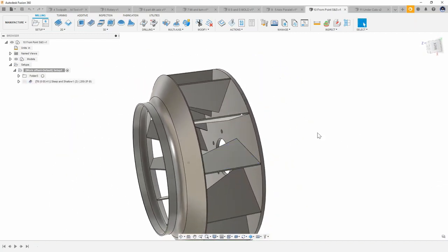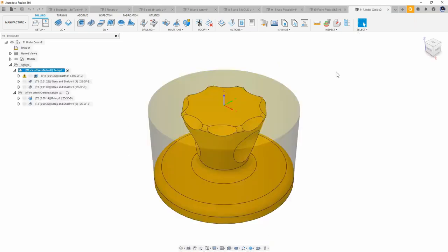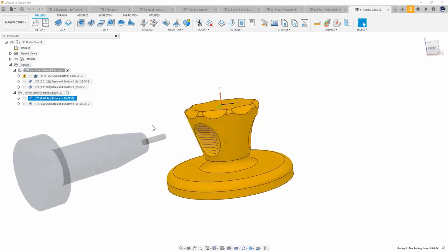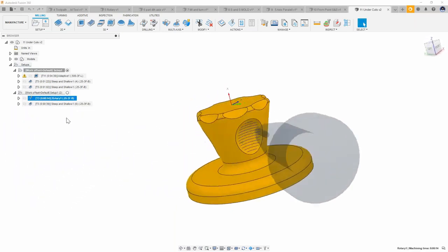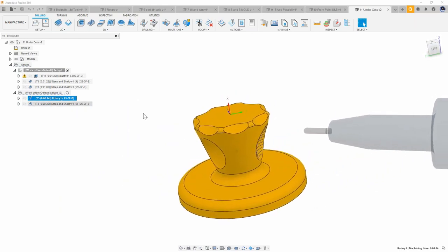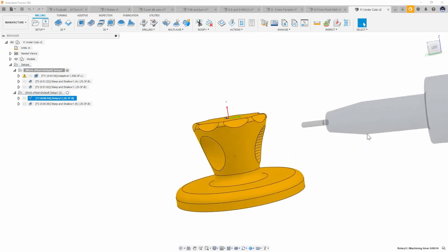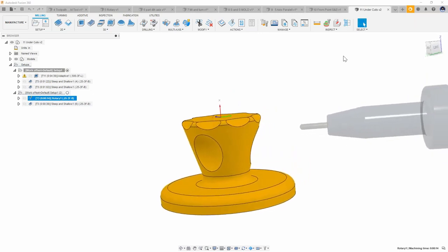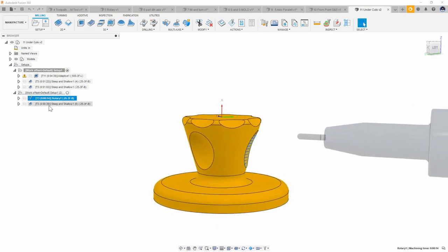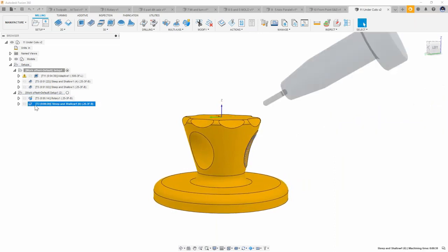The last thing that I have to show is just some of the undercut capabilities and that 4th axis that I was showing. We could obviously do some rotary strategies in Fusion and trim them to certain areas, but we can even do that with steep and shallow. Now, the limitation with rotary here is that rotary is for 4-axis only. So if I wanted to tip my tool at a certain degree, I wouldn't necessarily be able to do that. But steep and shallow, because of its multi-axis controls, allows me to do something like that.